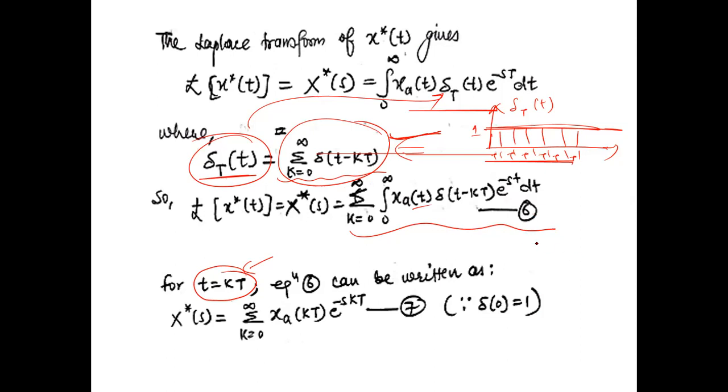Okay, that means if you have an analog signal like this, and you divide this signal into, let us say, k samples, 1 2 3 4, like k samples, the difference between each sample is t. So you have total samples for this duration t as k, so total time t will be equal to k into t, right?